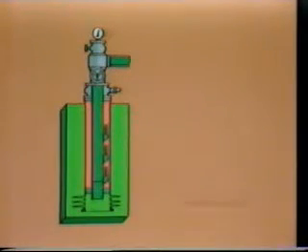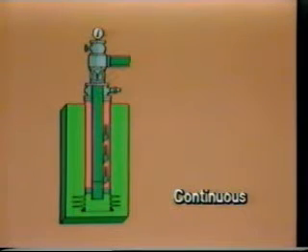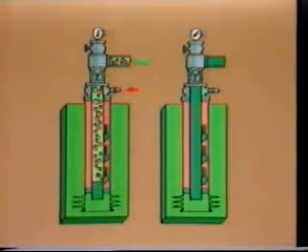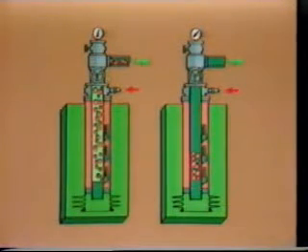Continuous flow gas lift relies on the constant injection of gas lift gas into the production stream through a downhole valve. Intermittent or intermitting gas lift allows for the buildup of a liquid column of produced fluids at the bottom of the well bore. At the appropriate time, a finite volume of gas is injected below the liquid and propels it as a slug to the surface.